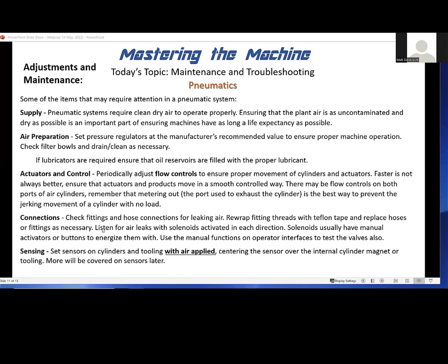Also check for electrical connections. It's the same thing. You have individual solenoids, sometimes like this, and these have a special little wiring diagram on them. Usually it's 1, 2, and 3 pins: positive DC, 0 volt DC, and a ground. And in some cases, you definitely want to apply the ground. In other cases, it doesn't matter. Most of the 24 volt ones, I don't worry too much about ground because your negative DC is grounded anyway.